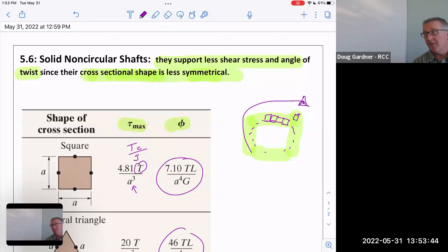And by the way, that's St. Venant's principle. In other words, when you grab the ends and tweak on them, weird stuff happens right around there because of how you grabbed it. But as soon as you get a little ways away from it, then it starts to even out. That's St. Venant's principle. And so what you said is the thing. That's a really good point.